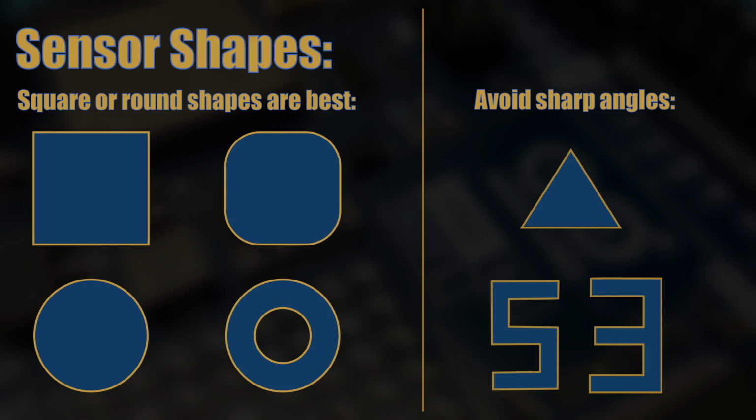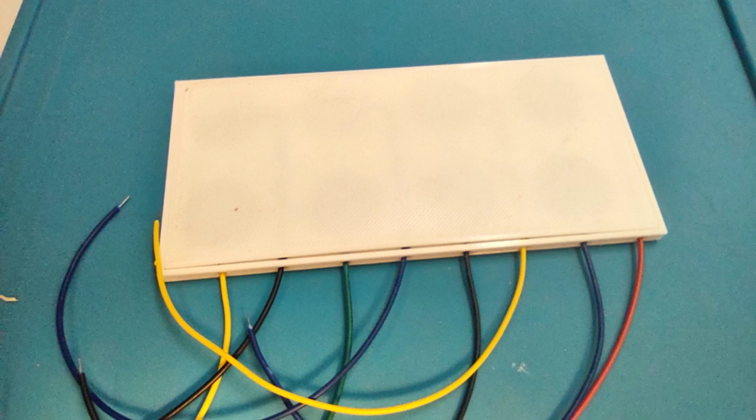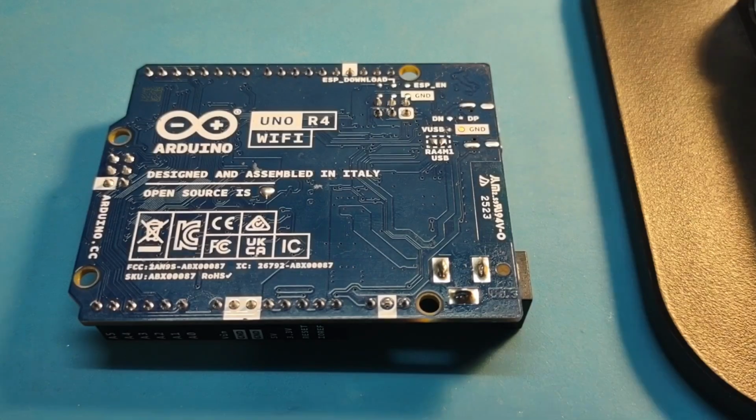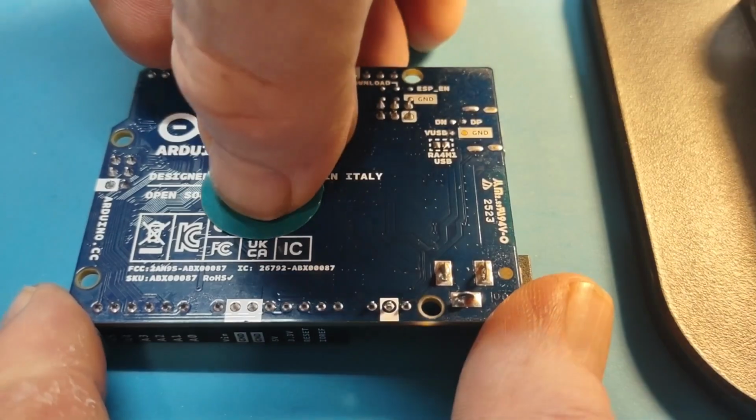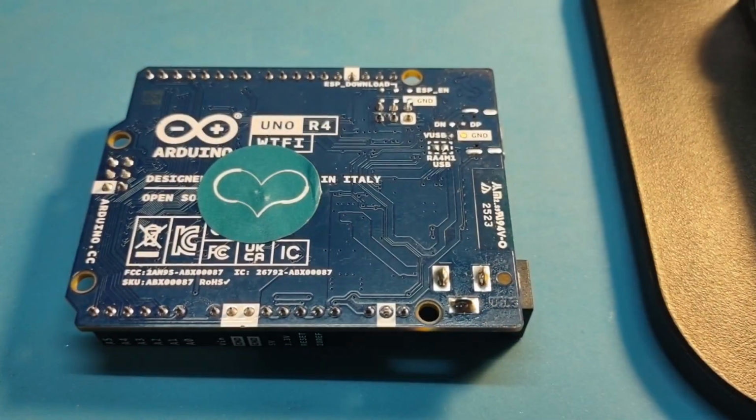These sensors use mutual capacitance, which is something the R4 can do, but it's not implemented in the library yet. That's coming soon. The sensor needs to be covered by something. Touching the electrode directly risks sending ESD to the chip. The choice of material and its thickness will have a great effect on how well the sensor detects touches. Try to keep the covering thin and use a material with high electrical permittivity.